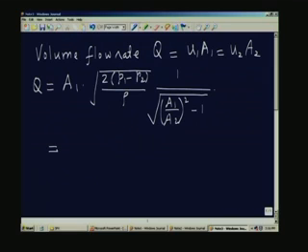This can also be written down as, instead of a1 I will say a2 multiplied by a1 by a2, and then I will adjust it with the denominator here. Therefore, this also can be written as a2 square root of 2 delta p by rho, where p1 minus p2 I am going to call delta p, and instead of a1 I am putting a2 here.